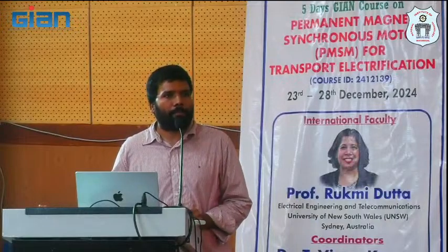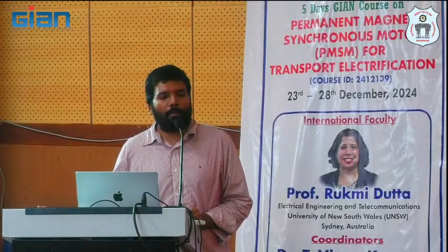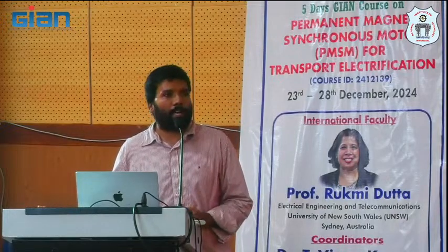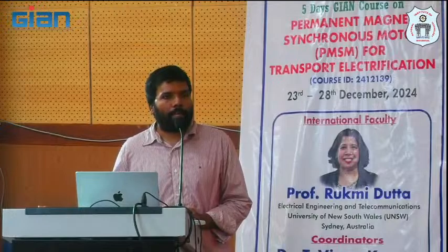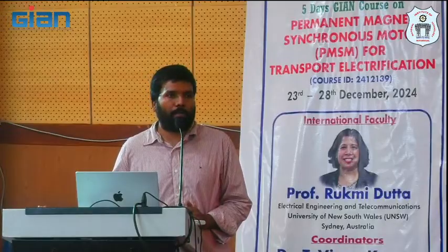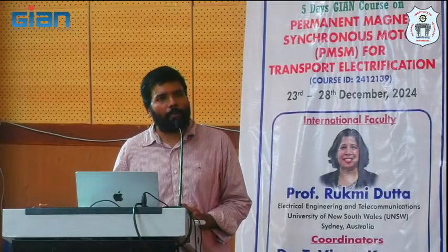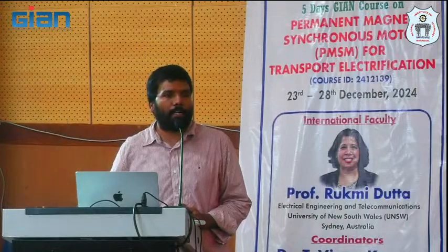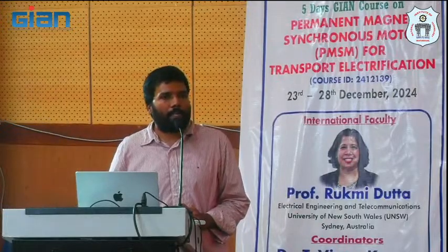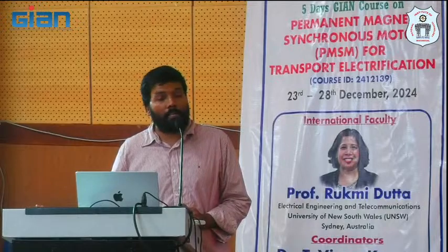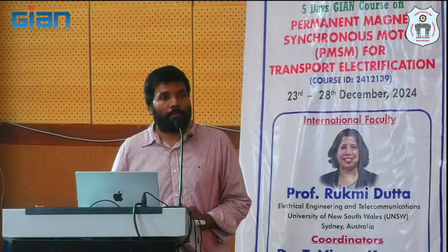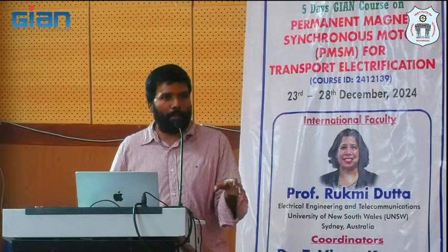One more important thing: the drawback of open loop control is that there is no control on the current. If you want to control the current, you need to take precautions even though it is operating in open loop. In industry, how are they adopting this? We have a Siemens Centre at NIT Warangal. They operate electrical drives, industrial drives, using the simple V/F method in open loop, and they are able to control the current even though it is operating in open loop.